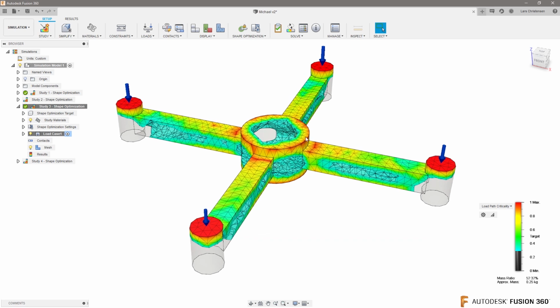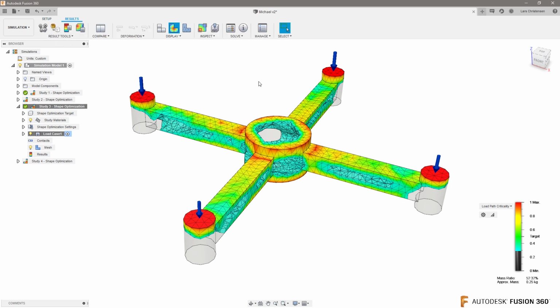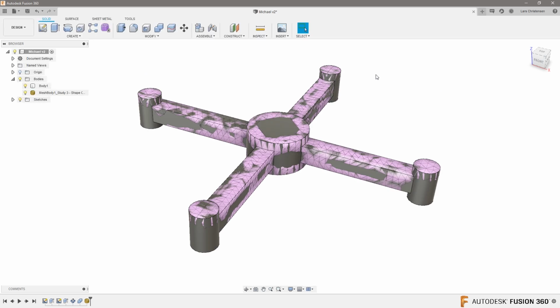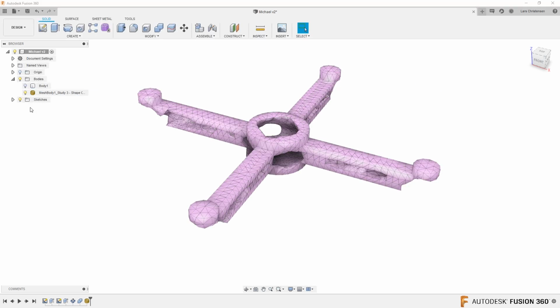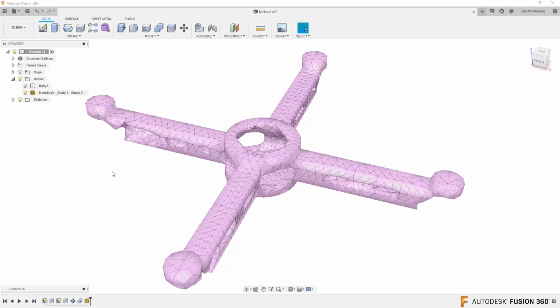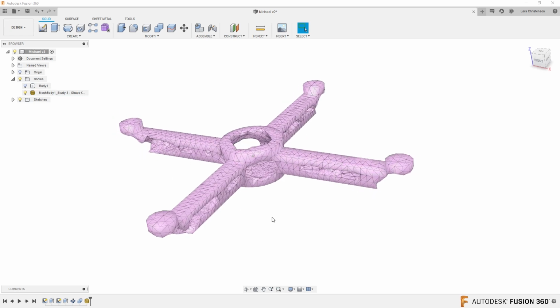And what is really cool about this, to wrap this up, is that if I go to the results section up here, you can actually promote what we're seeing on the screen. If I click on this promote button, I can go over here and say to the model workspace and hit OK. And now I'm back in my workspace, and look what I got. I got it out as a mesh. And if you've watched my videos before, you now know how you could possibly convert this into a solid, or you could of course also just start sketching, using it as a reference and model things away.